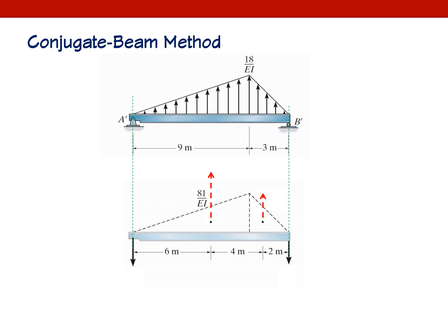To do so, I need to find the reaction first, because in this case my beam is not in equilibrium since I have no reaction calculated yet, so do not jump into drawing a shear force diagram and then a bending moment diagram. Always calculate reaction first.